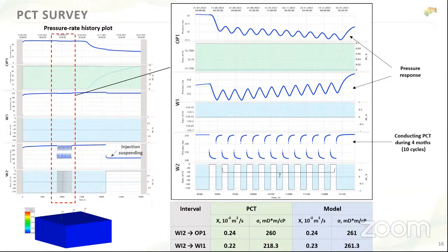And we have an additional limitation of time. If the reservoir properties are low and the distance between the wells is too far, then it might happen that the duration of the test should be incredibly long. Maybe if we have 1 millidarcy and 5 kilometers between the wells, maybe it would require a year to do the test. So it's not possible to do it in a reasonable time.